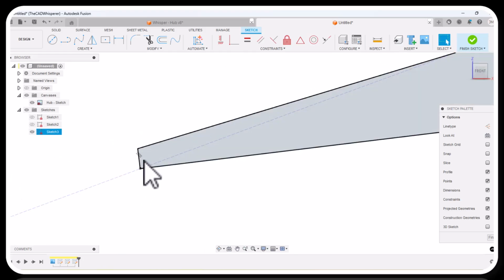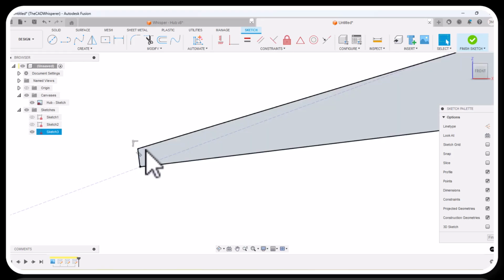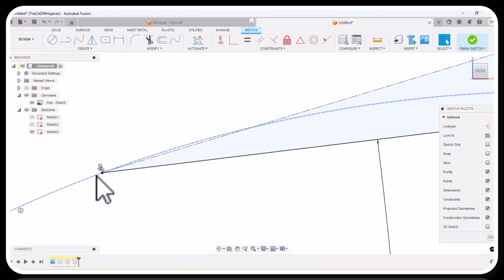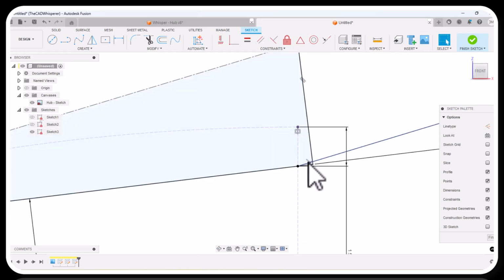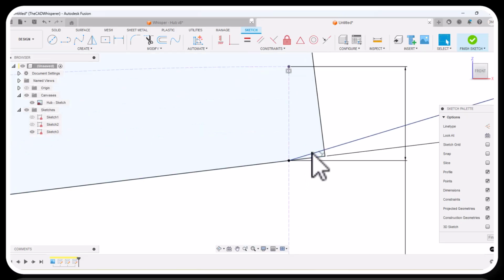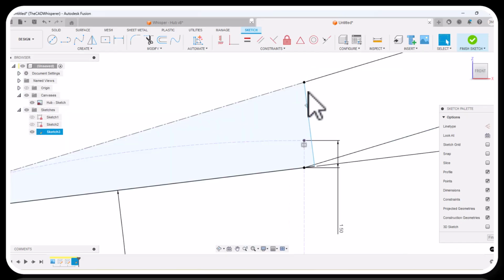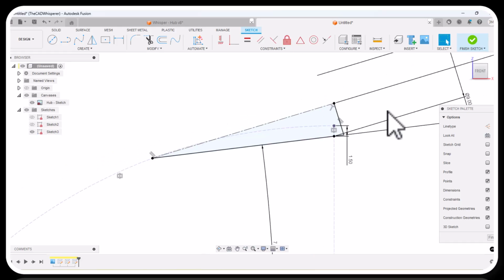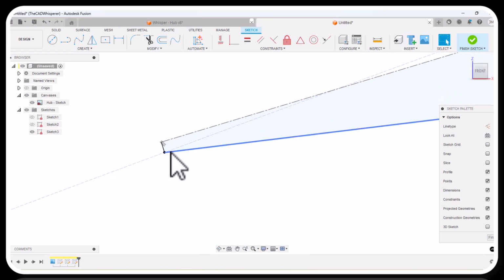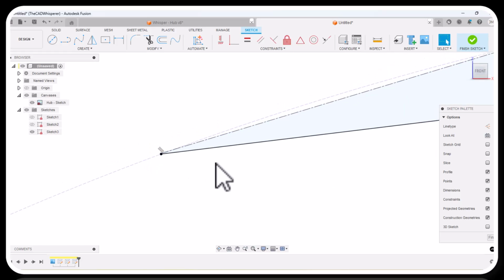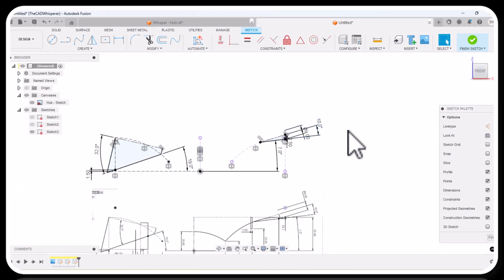There's a short little line right here perpendicular to the center line, or parallel to the line at the other end, and actually it's perpendicular down here to this. I want this line, it doesn't really matter, but I want it perpendicular to the center line. So let me delete that perpendicular because we're going to revolve about this. So I prefer to do the perpendicular about the axis of revolution. Okay, so now it's black again. And so then this line is parallel to this short little line over here. It's fully defined. All right, we're ready to start creating some geometry.